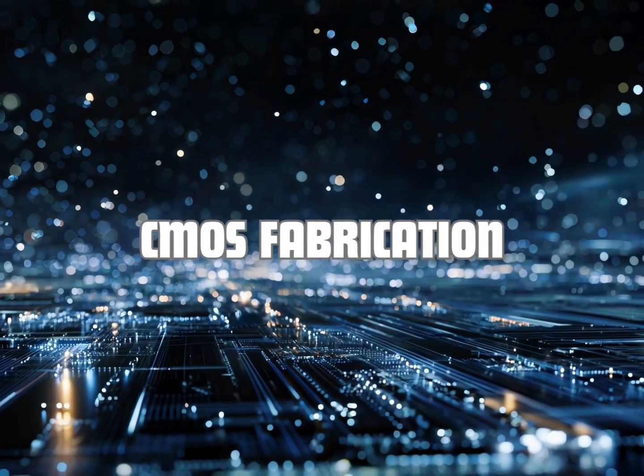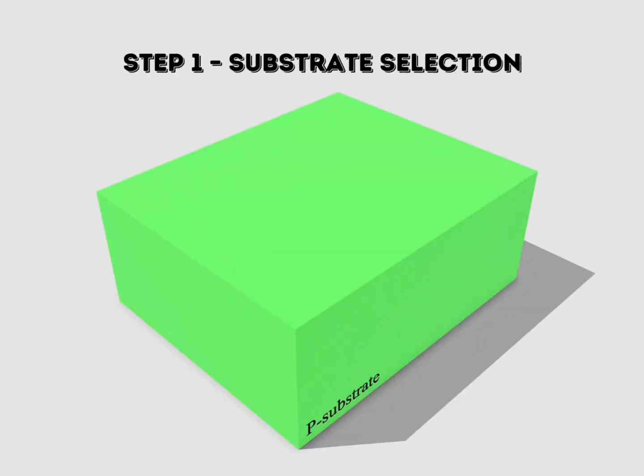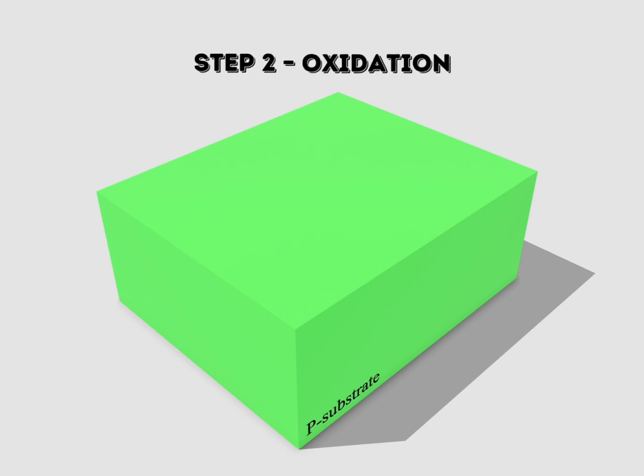Next, let's dive into how CMOS is fabricated. Step 1. Substrate selection. We begin by selecting a P-type silicon substrate as the foundation of our entire fabrication. This wafer is usually made using the Czochralski process, ensuring high purity and a uniform crystal structure, which is crucial for consistent transistor performance.